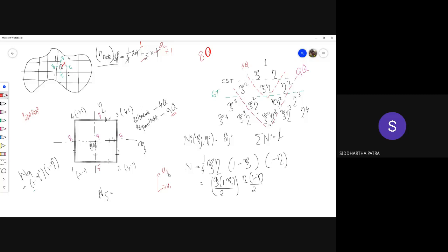And the number of degrees of freedom is proportional to the total number of nodes, not per element. That is the total number of degrees of freedom. And actually your global stiffness matrix, the size of that is NDOF times NDOF. That means that is the number of equations you are supposed to solve, either for the degree of freedom or for the reaction force.